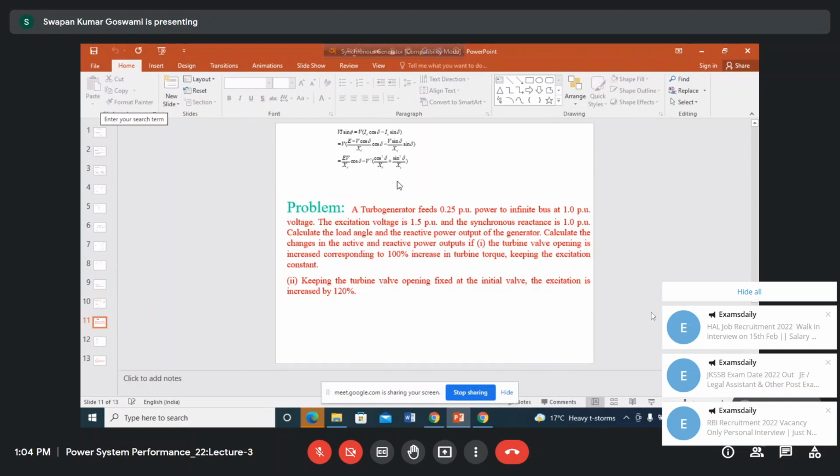It is very similar to the cylindrical rotor machine. Also, we have discussed about the synchronous motors. We have seen that synchronous motors may be operated at a no load condition under overexcited situation, and if the motor is overexcited, then it can deliver reactive power.